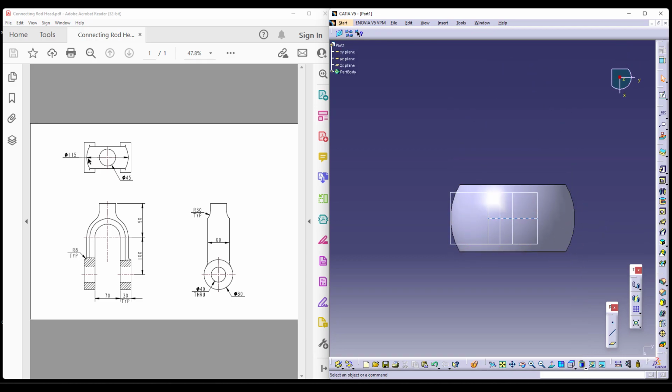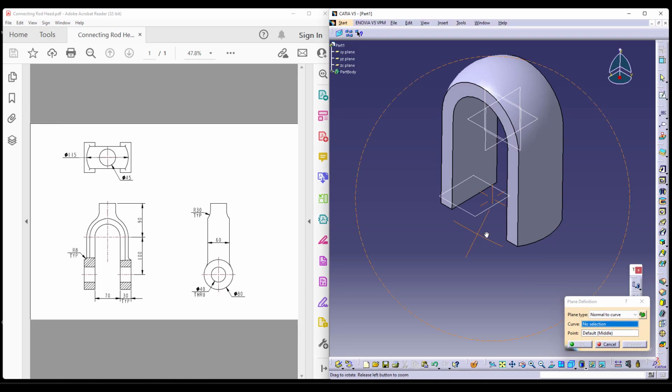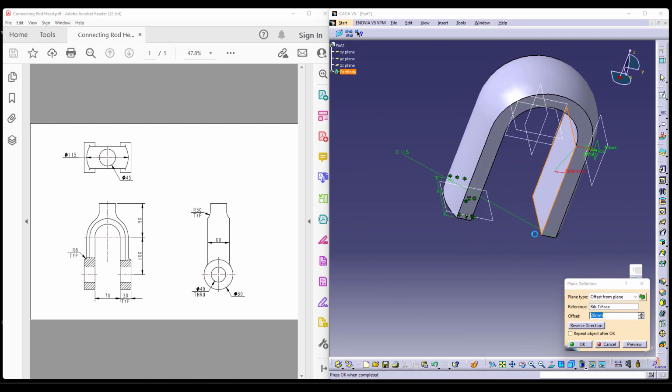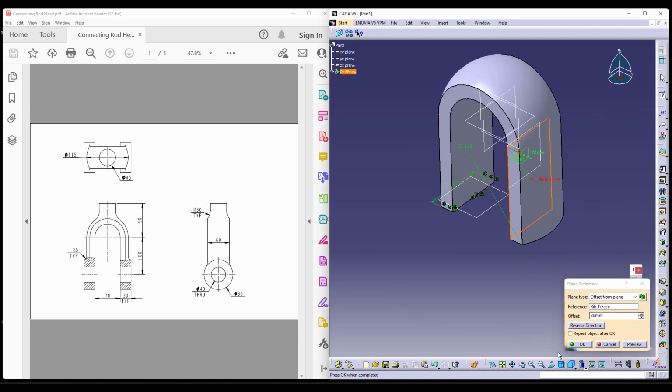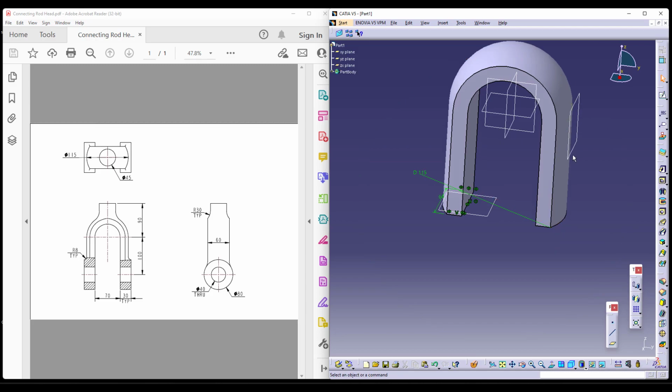The diameter shown here is 115. Now, continuing with the addition of materials, we have an 80 circle which is added at 30. So let's take a plane. I am taking a plane because this surface is a curved structure. It will be easy for us to make it and add material up to the next surface rather than doing it on the curved surface.